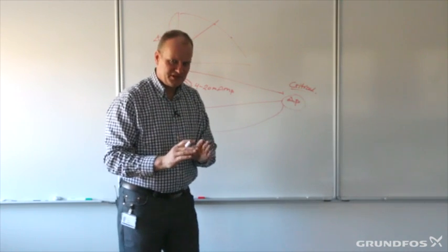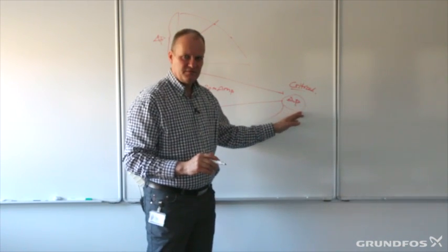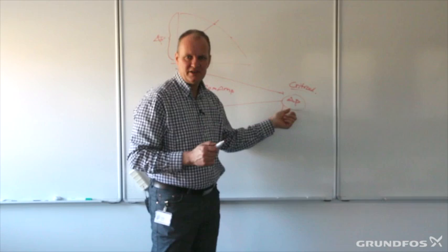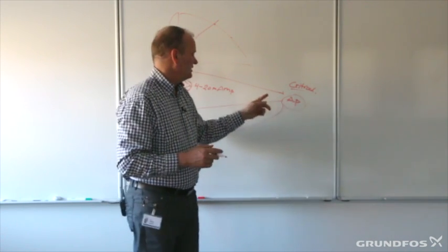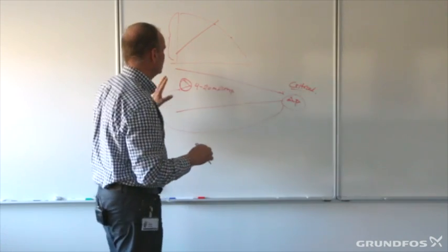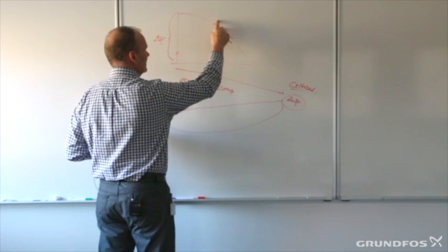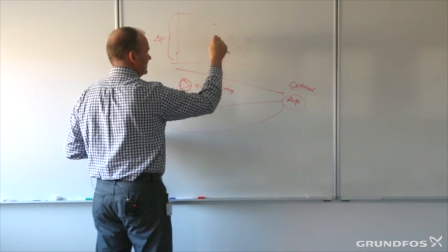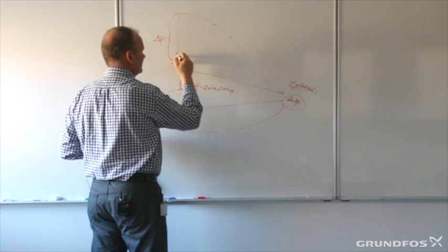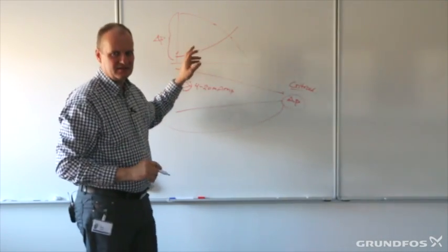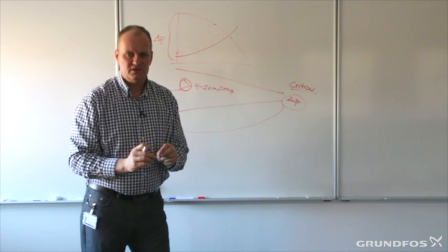But if we do this, monitoring the differential pressure needed at the critical spot in the system, then the pump will not need this kind of control curve, but it will allow the pump to operate on the exact system characteristic.